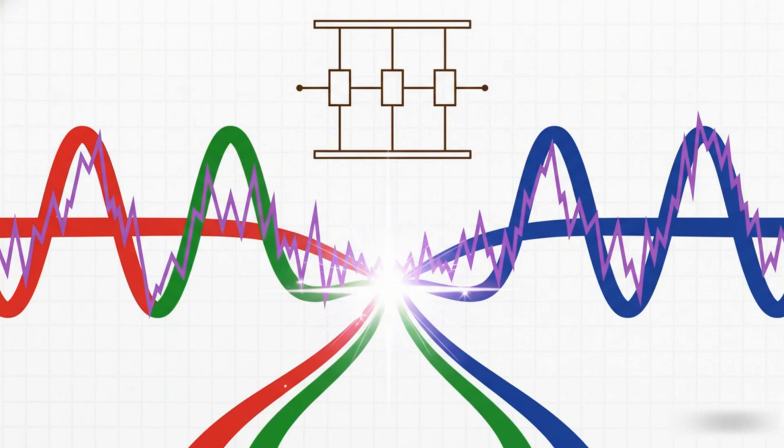To create this, we basically just use 3 of our H-bridge legs side by side for a total of 6 switches. We apply the same PWM control to each leg, but we give each one a reference sine wave that's shifted by 120 degrees from the others. This creates 3 beautiful AC outputs that form a balanced 3-phase system. And here's a really fantastic bonus. In a balanced system like this, a whole group of harmonics called triplet harmonics, that's the 3rd, the 9th, the 15th, and so on, they just naturally cancel each other out. So we get an even cleaner output, basically for free.